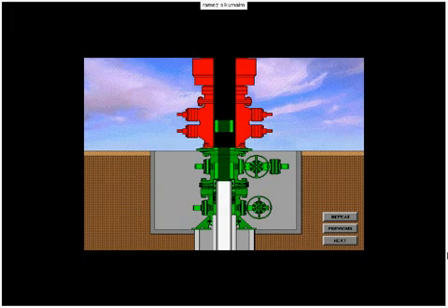Upon completion of the BOP tests, the wear bushing running tool is made up on the drill string, and the wear bushing installed on the running tool. The wear bushing is then lowered through the BOP system until located in the casing spool bowl. The wear bushing is locked in place either by lockdown pins in the casing spool flange or by lockdown pins located in a lockdown flange. The running tool is then removed, and the drilling operation can resume.